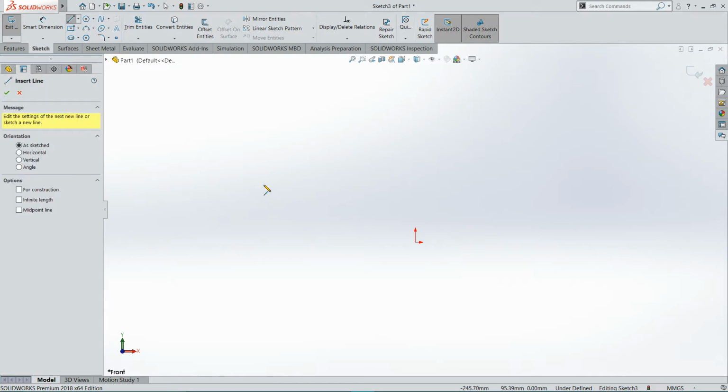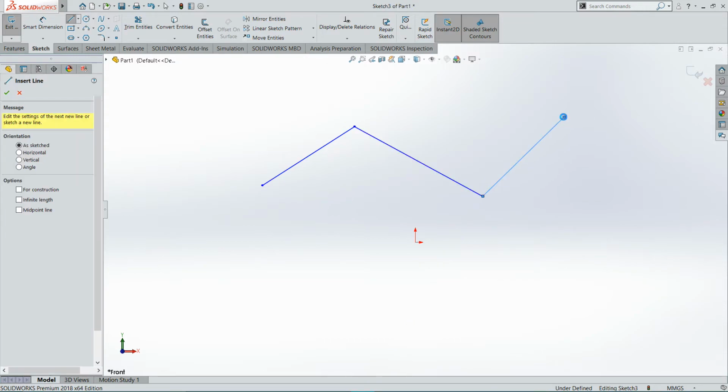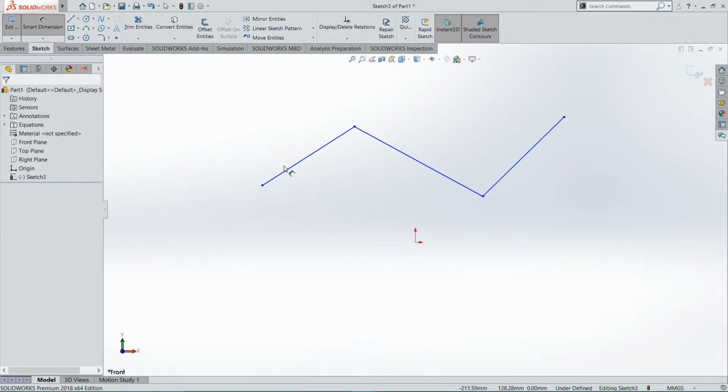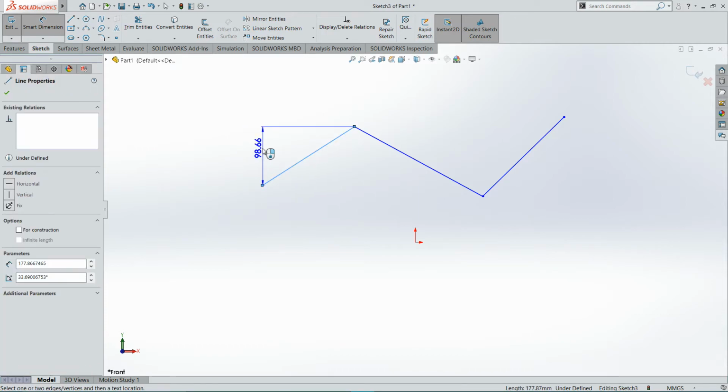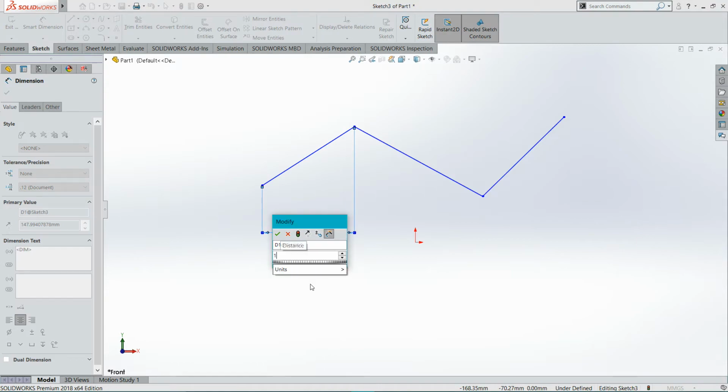Let's use the dimensioning. How to provide dimensioning. Here you can see you can assign vertical along the length and horizontal. Same on the bottom side. Once you fix, click on right click. Now it is fixed. It will not change. Then place it and provide your required dimension.